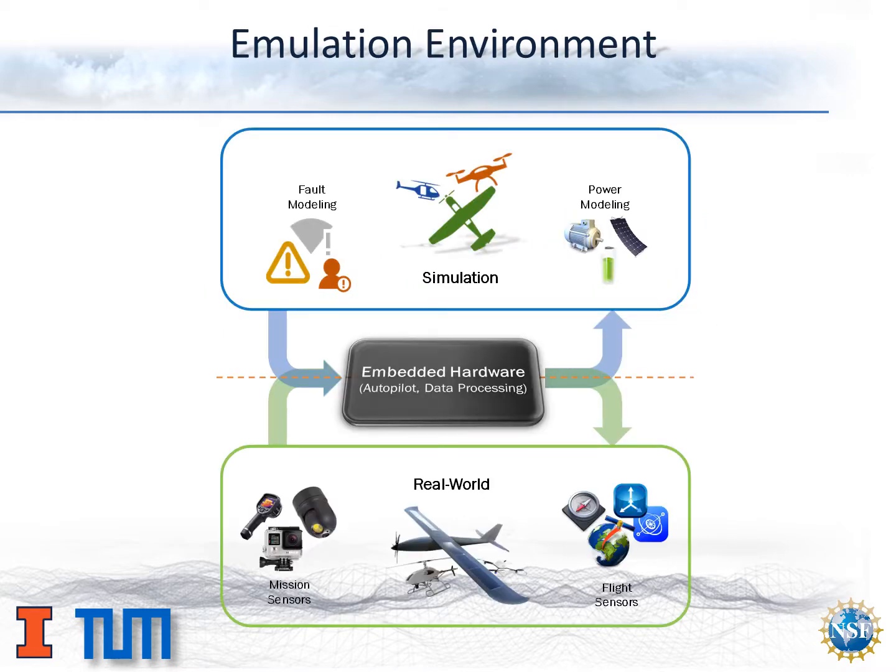We created an emulation environment that allows us to rapidly test and evaluate autopilot and embedded hardware. In the emulation environment, the same embedded hardware that is used to control the aircraft and gather data from mission and flight sensors is connected to a simulation environment. The interface of this connection emulates the sensors and actuators, making embedded hardware oblivious to if it is running in the real world or in the simulation.